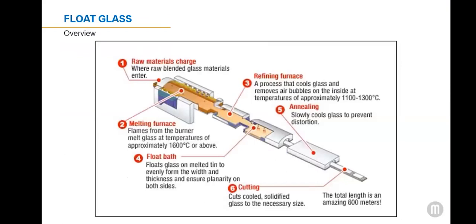The float glass process is the most common method of flat glass production in the world. This process basically involves melting silicate, lime, and soda in a furnace and floating it onto a large bed of molten tin, hence the name float glass. This mixture slowly solidifies over the molten tin as it enters the annealing oven, where it travels along rollers under a controlled cooling process. From this point, the glass emerges as one continuous ribbon and is then cut further and processed to fit the customer's needs.